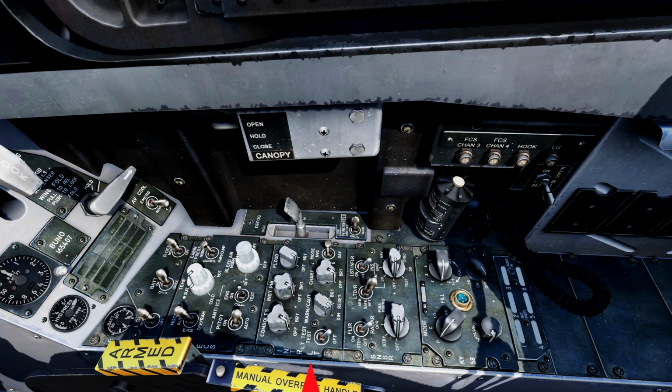Below the ECS panel we have the internal lights panel. On this panel we have lighting control for the left and right consoles, the instrument panel, a general floodlight, the warning and caution lights, and the chart, which is basically the knee board. We also have a test switch for all warning, caution, advisory, and instrument lights, as well as a switch for either day, night, or NVG mode. To the right in the internal lighting panel is the lever for defogging, and below that is a switch for anti-icing and rain on the windshield.